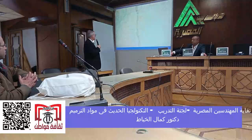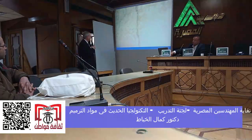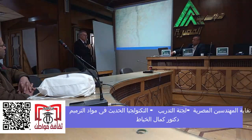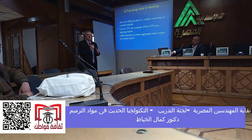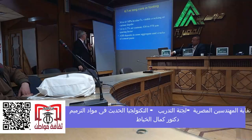Next. So this is a close view of the cracks. Cracks can be a couple of millimeters up to 10 millimeters in thickness. They're very large cracks. Next. So they took some cores, 6.7 meters, and they determined in situ the strength is not bad. After 50 years, the strength is not bad, but there's a lot of visual cracks.